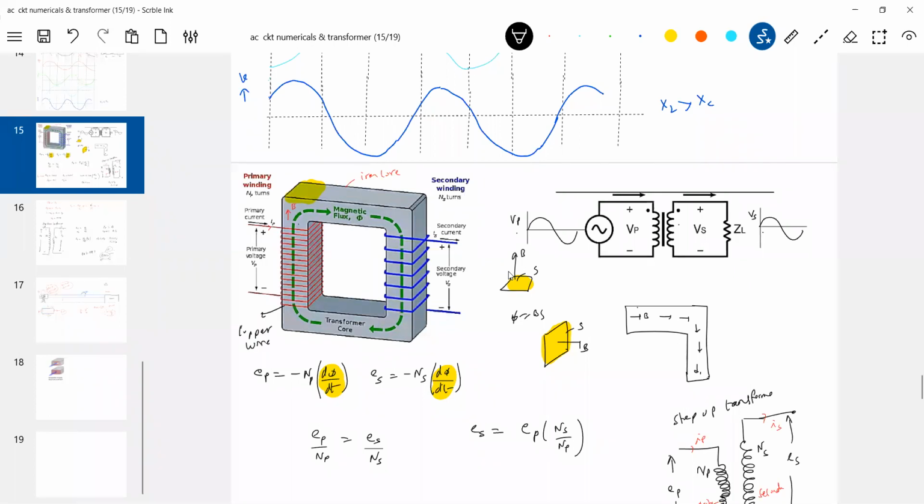And we know whenever a current flows through a metal, heat should be generated. So to minimize these I square R losses in the windings, what shall I do? Go for R equal to rho L by A. So what sort of copper wire should I use for winding? A thicker one, no? If the area of cross section is more, resistance will decrease. If resistance decreases, I square R in the winding decreases.